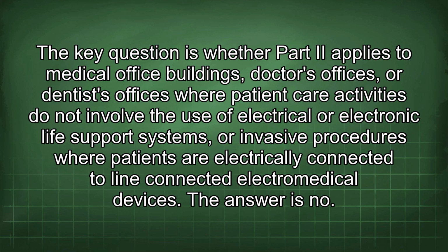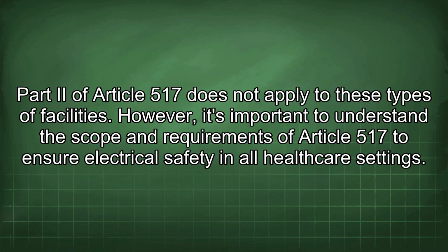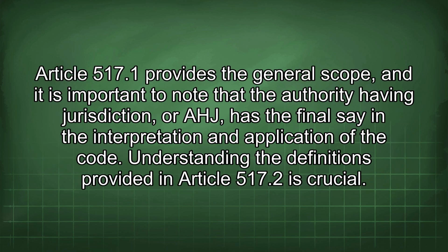The answer is no. Part II of Article 517 does not apply to these types of facilities. However, it's important to understand the scope and requirements of Article 517 to ensure electrical safety in all healthcare settings. Article 517.1 provides the general scope, and it is important to note that the authority having jurisdiction, or AHJ, has the final say in the interpretation and application of the code.